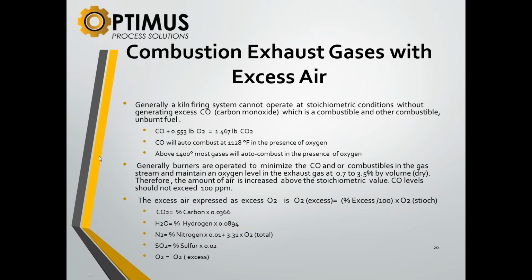So sometimes the flame temperature can be higher because you reduce the oxygen, and you might get a little carbon monoxide off the flame, but you'll get a hotter flame. Interesting. So there are other things going on here, which is why it's so important that your oxygen level be as low as you can get it, and not exceed 100 parts per million on the carbon monoxide. So that's something you're playing with, and it's not that easy.